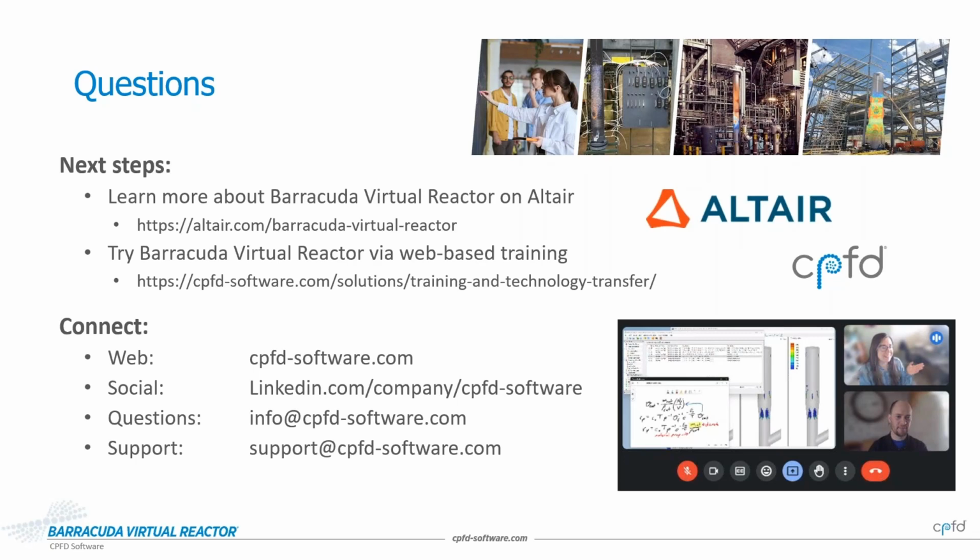Other users, if they have vessels that are too big or too complex to do that, can use the information from flux planes. You can measure what's coming out of one system and use that as the input to the next system as you're setting that up. So it just depends on what the system looks like. But if you could fit it all in one model, that would probably simplify your life so that you wouldn't have to do a whole lot of work on the boundary condition side of things.